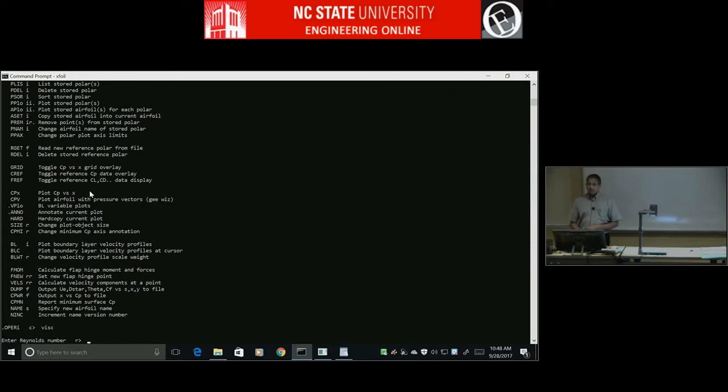We'll run this at 3 million, and so you can put the Reynolds number here as 3, 1, 2, 3, 4, 5, 6. That's 3 million, but if I remove a 0, it still looks more or less the same. It's so easy to make a mistake, right? I put 3 and 5 zeros, and if you do this without noticing, you'll run this analysis for 0.3 million, thinking it's 3 million, and it'll all come out wrong.